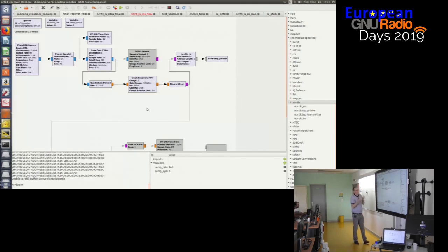But that's normally what is done inside a real chip. Well, you have to try with the threshold values because it's not well documented. You have to fiddle a little bit with that, but it works quite well. After that, you've got a low-pass filter, again to limit the reception bandwidth.